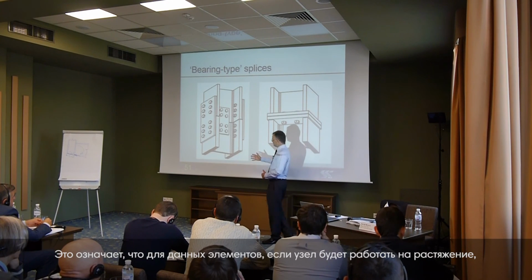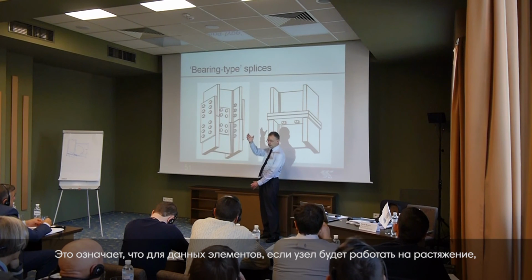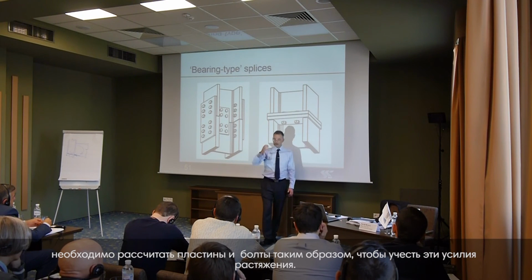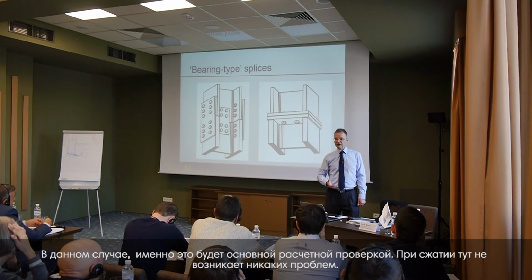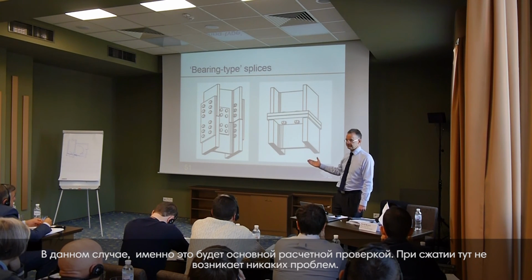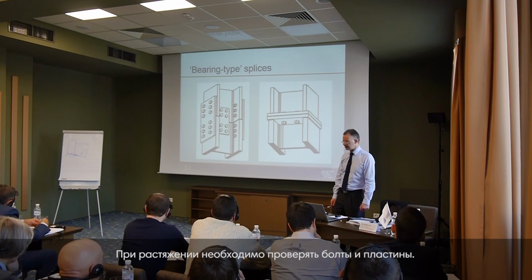So that does mean that for this detail, if we had to design that for a tension, then the bolts and the plates would need to carry the tension force, and that would be the dominant design check. In compression, no problem. In tension, we would need to check the bolts and the plate.